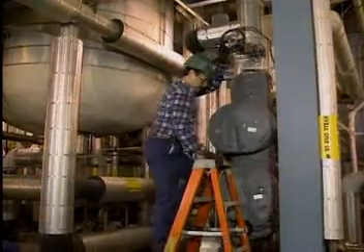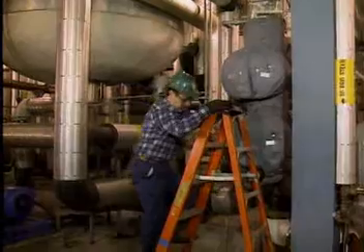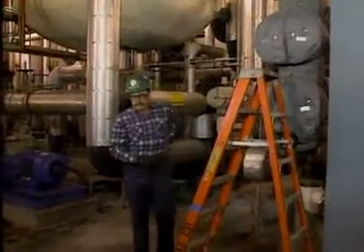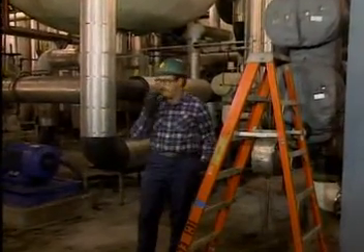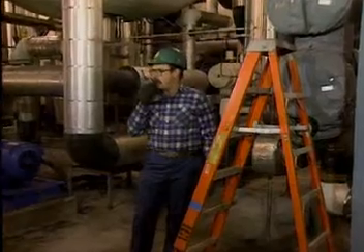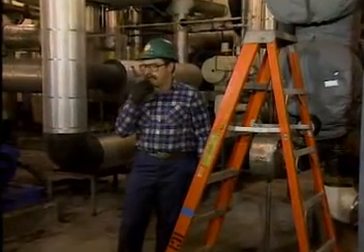At this point, the startup is complete and the heat exchanger is in operation. After the operator reports to the control room that the unit is in operation, the control room establishes flow through the unit. Shell and tube heat exchangers are commonly used in a variety of processes, and each may have a different operating procedure. But remember, always follow your facility's operating procedures when shutting down any heat exchanger.